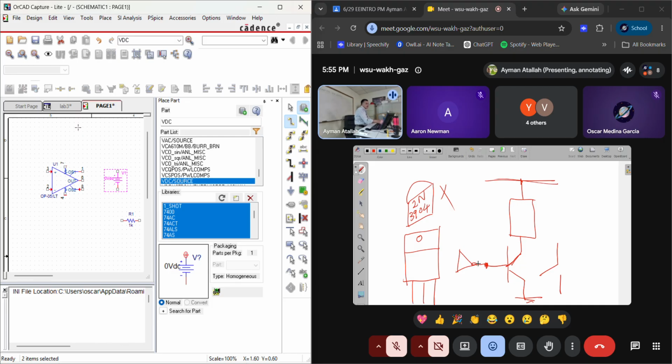The power doesn't directly come from the operational amplifier, because its current is too low, so it's used only to turn the switch on and off. The motor gets power from the DC power supply.